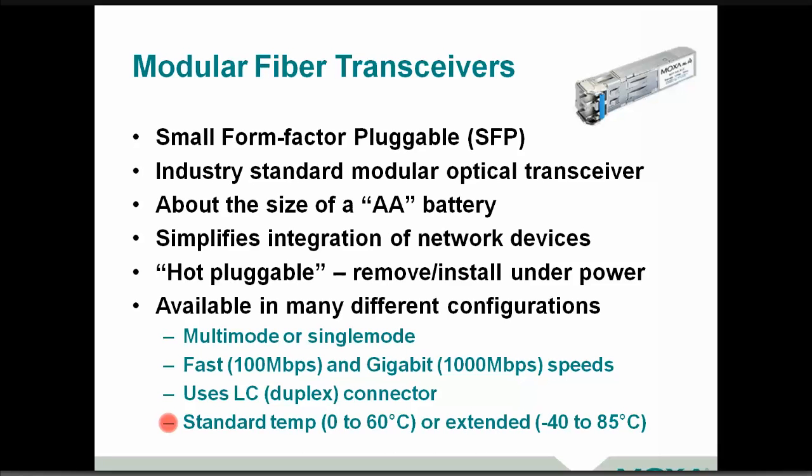So if you're doing a project outdoors, doing data collection for a PV solar array, or a municipal application, or an outdoor weather station, whatever this might be, you're going to want to make sure that you use the extended temperature rated for outdoor use, without having to have air conditioning on that control panel. So lots of good stuff. And again, maybe a little bit of review for some folks, but really great technology for doing that fiber connection at the fiber itself, utilizing modular fiber transceivers known as small form factor pluggable.